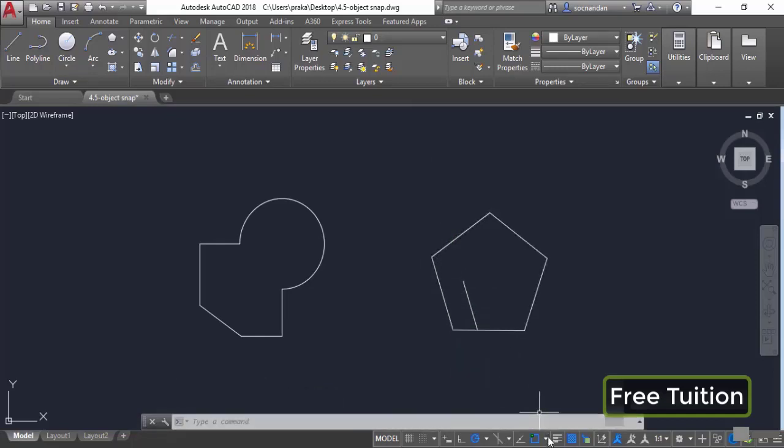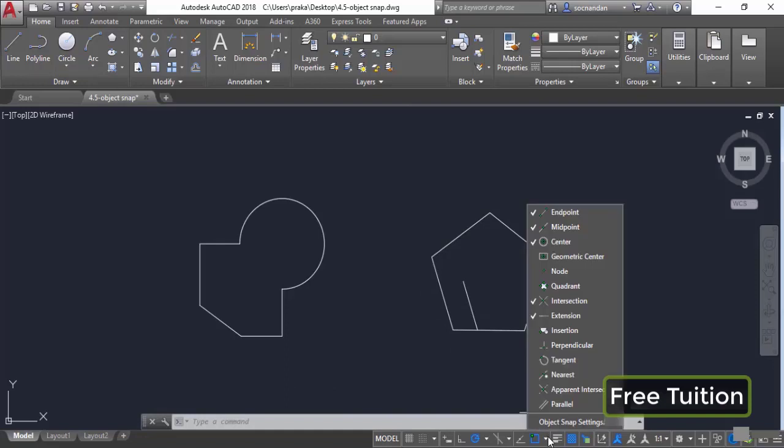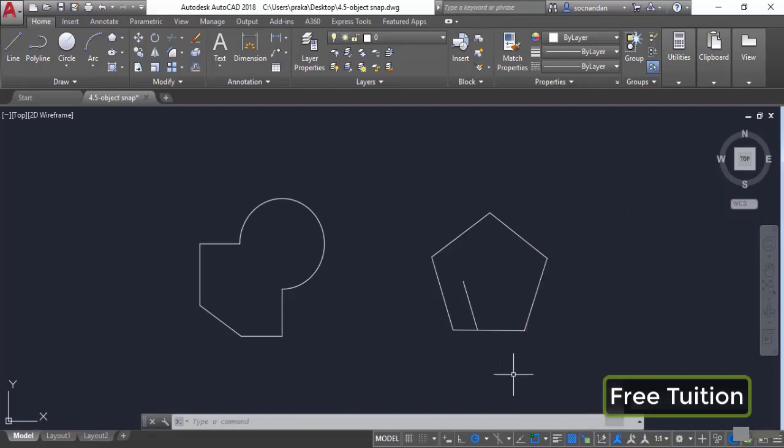So we have some other options also. Let's see that. Here we have this Nearest option, which should be turned off in most cases. The Nearest option is helpful if you want to click at any point on the curve. For example, in this case, we have an arc, and on this arc we have some well-known points like the quadrant and the center. But what if you want to click somewhere in between the quadrants? For that, you can select the Nearest option.